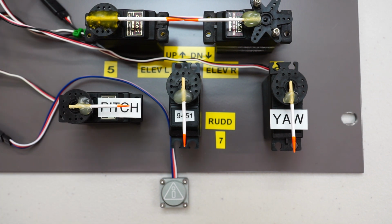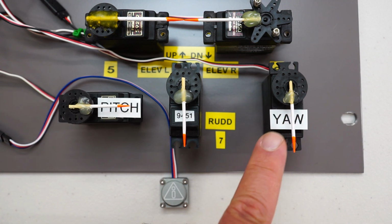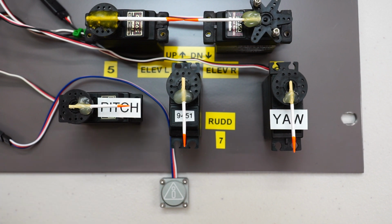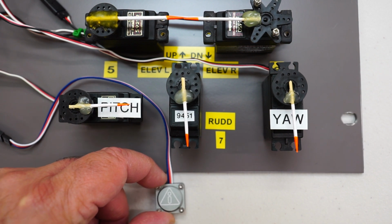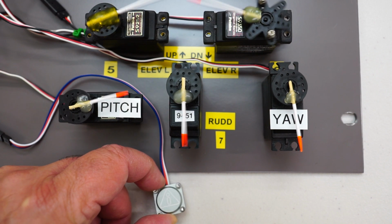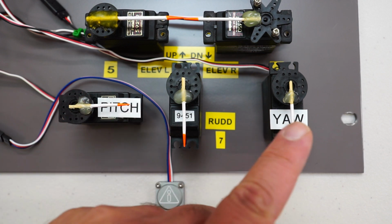However, there's another thing to be aware of, which is the fact that we can switch these guys off so they don't respond to any inputs on our radios. That's fine. However, just be aware that the gyro will still impact these servos, depending on what the gyro is doing. So even though we don't have any stick input, the gyro itself can still affect these two servos.